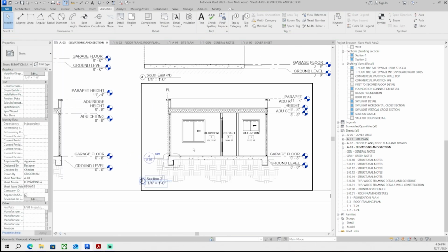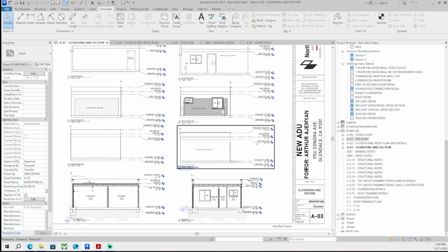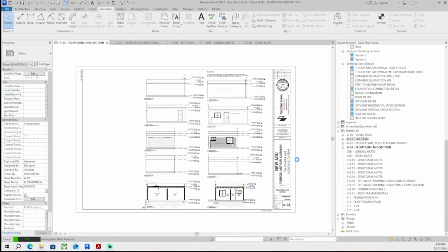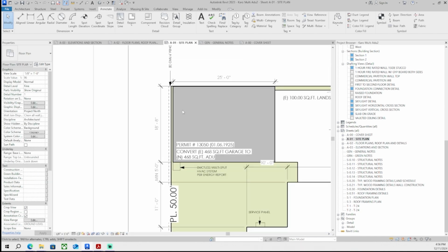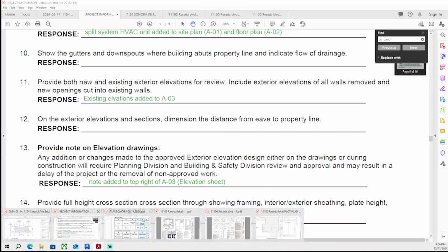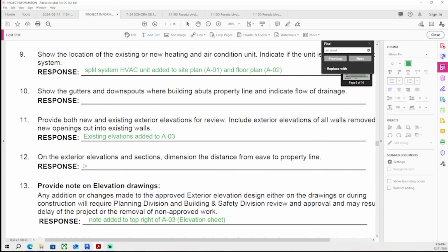So a few seconds ago, I was in the middle of saying something. You saw me looking at the 3D model. I do like looking at the 3D model in Revit, and I use the section box. There's a button you click on the left in the properties menu. It says section box. You click section box when you're in a 3D view, and you can drag down the section box and see what the floor plan looks like, what the section looks like, and you can cut through your 3D model, and it helps visualize it.